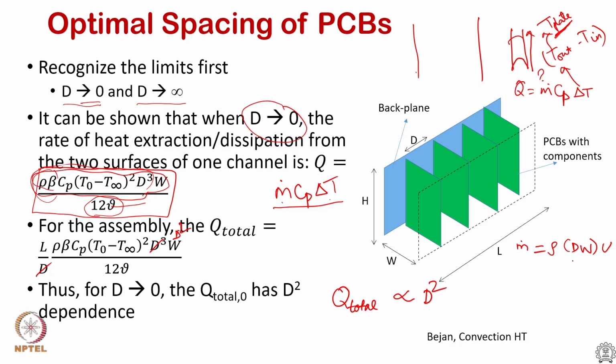So, how do I figure out what my velocity is? Because it is a natural convection heat sink, it is a balance between the buoyancy force, g beta delta T, where beta is the expansion coefficient, g is the acceleration due to gravity, and delta T is the same delta T we discussed here, being balanced by the pressure gradient.